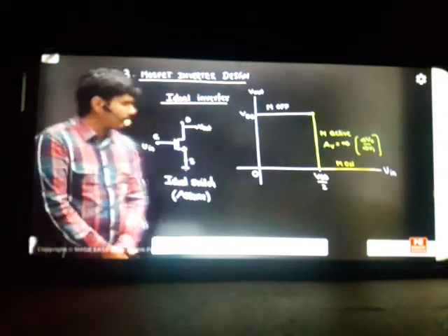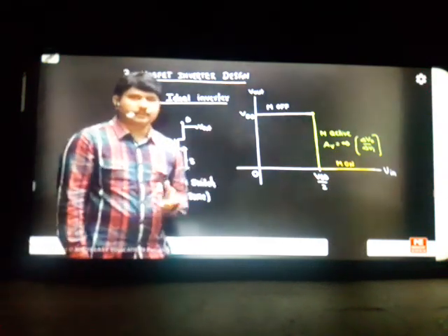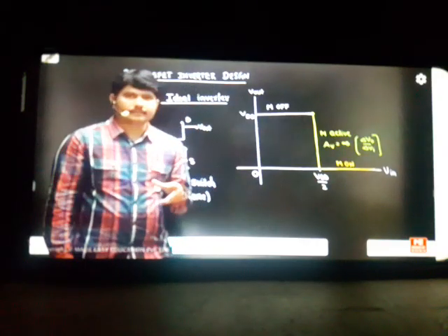So Divya, that's nothing but what I have explained. If you have a switch, when your input is low, the output should come as high. That is called an inverter. Low input, high output has to come. When the input reaches high, VDD by 2 and after, the switch comes into on condition, which will work like a short circuit, so the output will become 0. This is our switching characteristic.